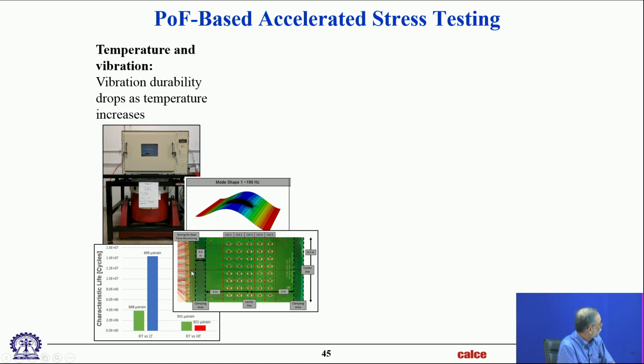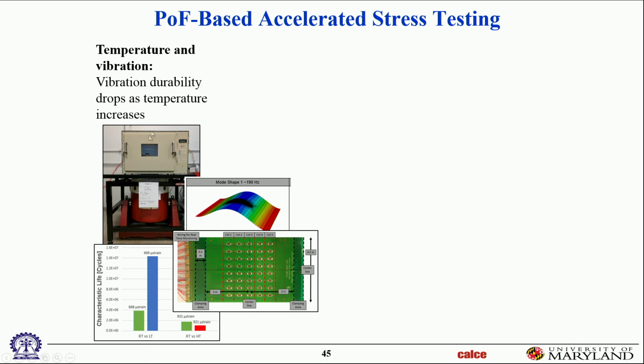So this circuit card was clamped along these two vertical edges, and then shaken out of plane. You can see it's shaking out of plane and deforming in this computer model. And then we do that vibration at different temperatures.